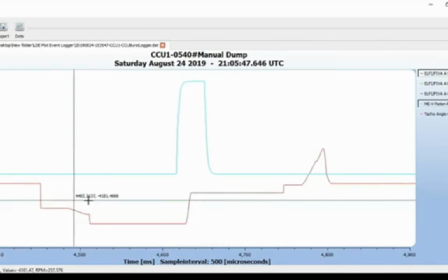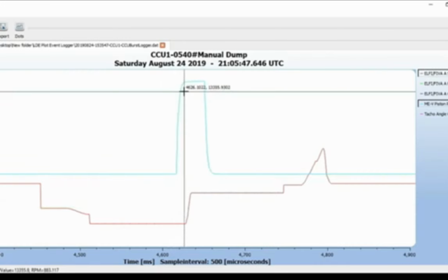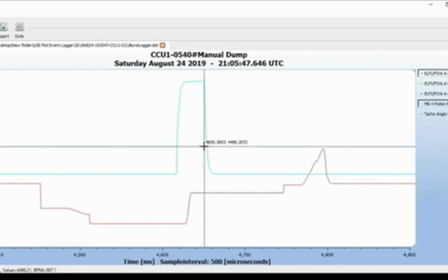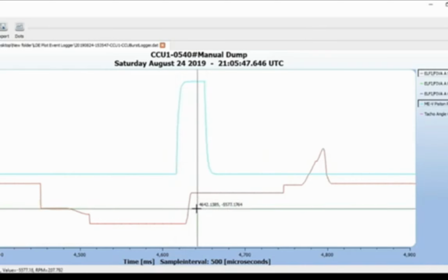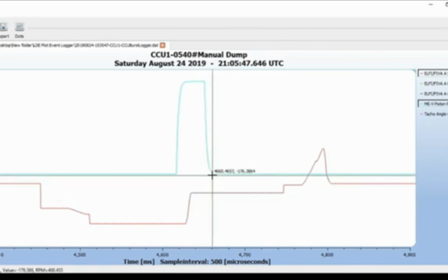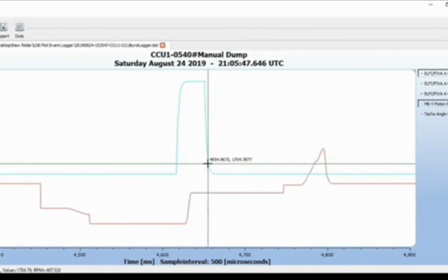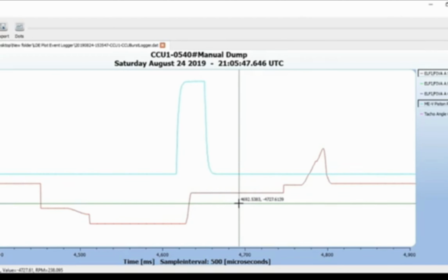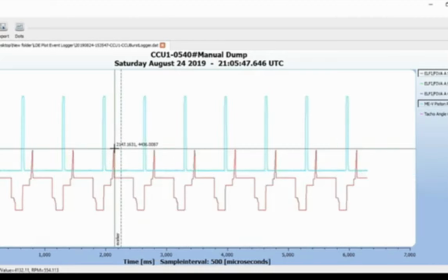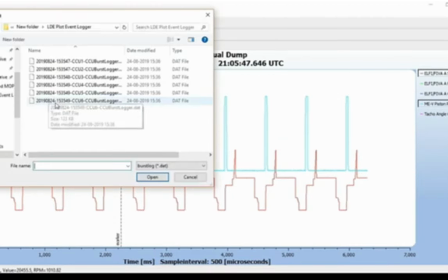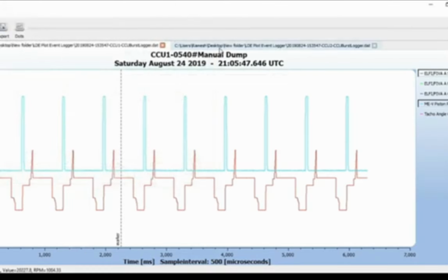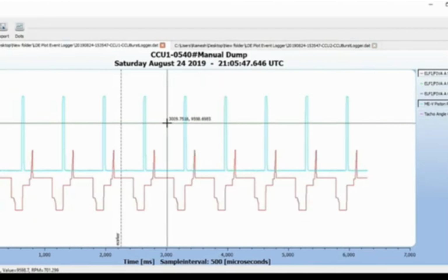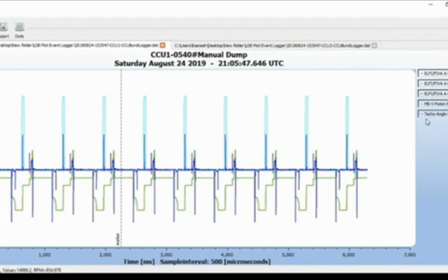You see the bottom line is showing the ME piston activated, and the upward flank is the activation, and the downward flank is the closing of the ME piston. The upward flank is not very important, but the closing, downward flank is very important, because that is what changes the compression pressure of that particular unit. This way we can easily understand what is happening, and if any error is there, we can easily compare with all units. Now I open both units, CCU1 and CCU2, for easy comparison.